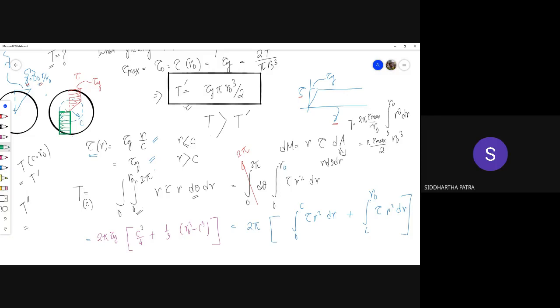As long as there was an elastic core, you can apply more and more torque, so there was some non-zero stiffness. And the moment you reduced the elastic core to 0, there is no further torque bearing capacity. It has reached its limit. There is a maximum limit of the torque that it can withstand.